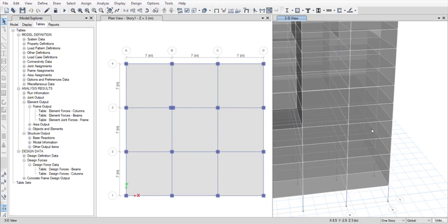You can do it in this way, or you can use the individual one by selecting 3 points. In this way you can draw a rectangle. If it is trapezoidal, use this tab. If it is rectangular, you can use quick draw slabs or areas.